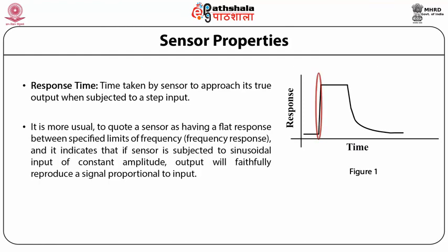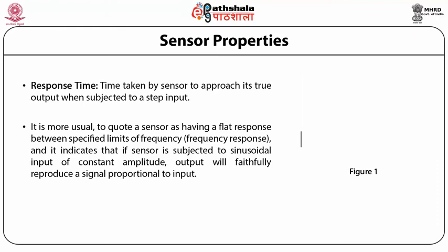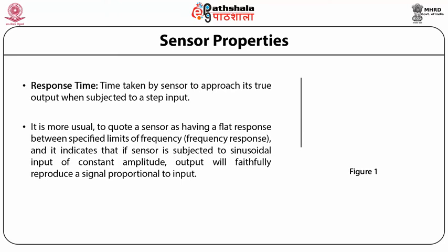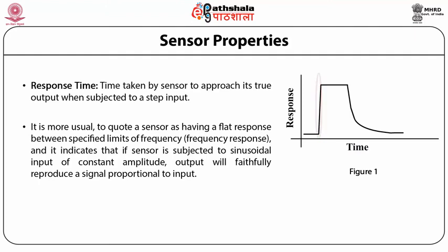It is more usual to quote a sensor as having a flat response between specified limits of frequency, that is frequency response, and it indicates that if the sensor is subjected to a sinusoidal input of constant amplitude, the output will faithfully reproduce a signal proportional to the input as shown in this figure.